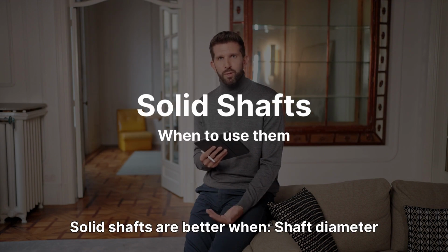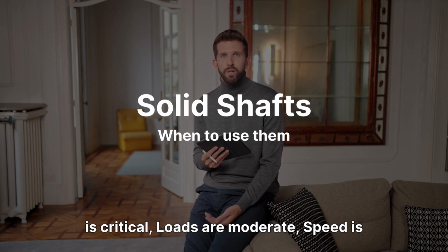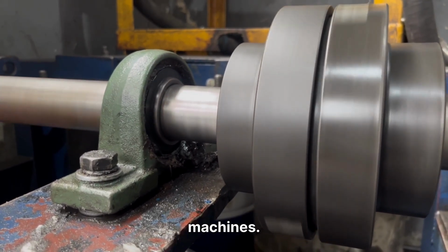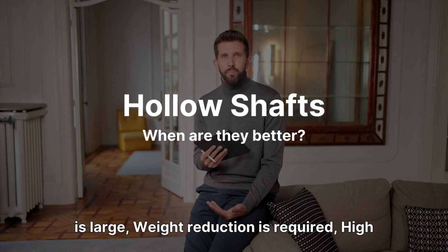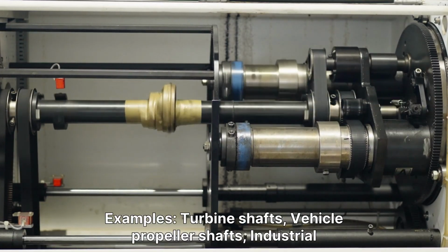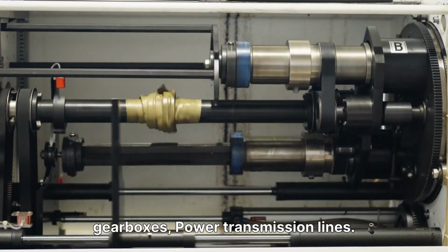Solid shafts are better when shaft diameter is small, manufacturing simplicity is important, cost is critical, loads are moderate, speed is low. Examples: small motors, simple gear drives, workshop machines. Hollow shafts are better when shaft diameter is large, weight reduction is required, high torque transmission, high rotational speed, long shaft lengths. Examples: turbine shafts, vehicle propeller shafts, industrial gearboxes, power transmission lines.